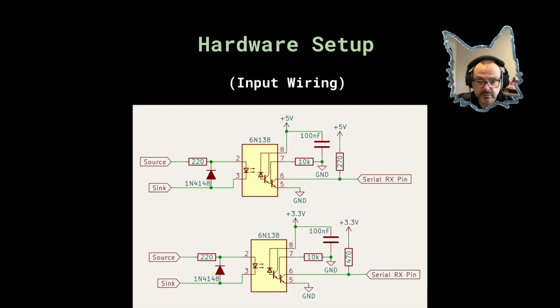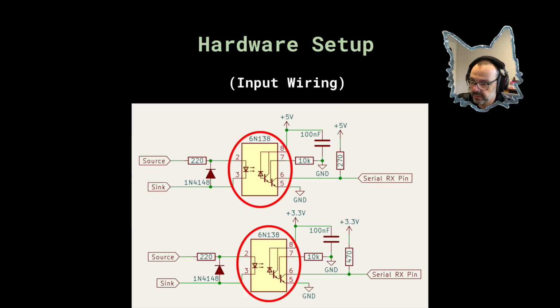The standard calls for complete decoupling of the two circuits. So in order to do this, we utilize a device called an optocoupler, which is this thing which I'm showing in the screen right now. So let's see if we can figure out what's going on here.